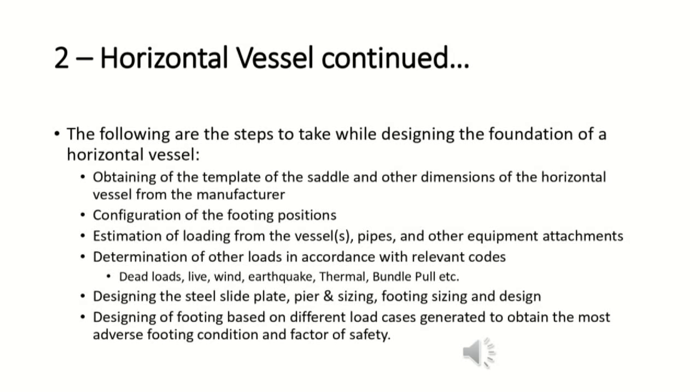The following are the steps to be taken while designing the foundation of a horizontal vessel. 1. Obtaining of the template of the saddle, which is the supporting plate connected to the horizontal vessel, and other dimensions of the horizontal vessel from the manufacturer. 2. Configuration of the footing positions. 3. Estimation of loading from the vessels, pipes, and other equipment which are attached.